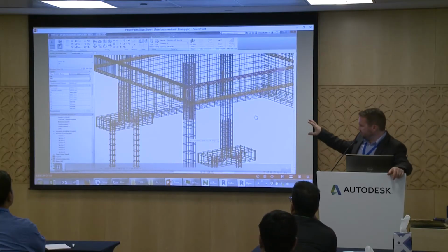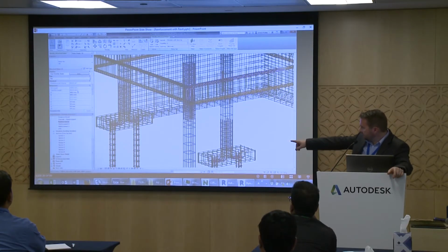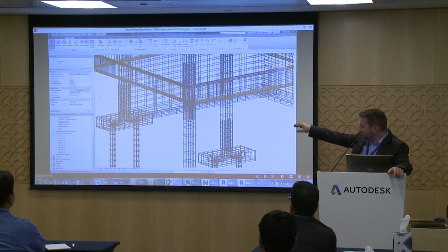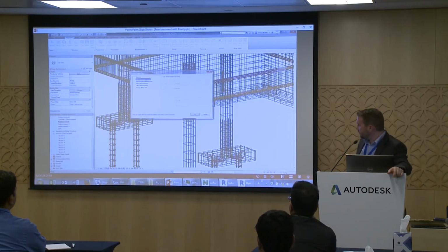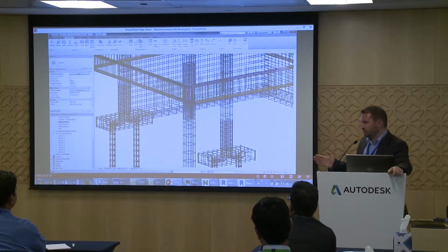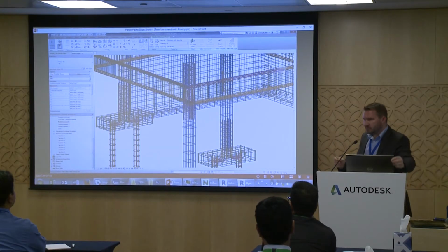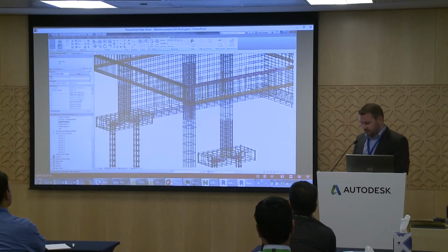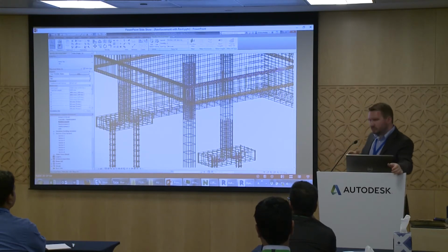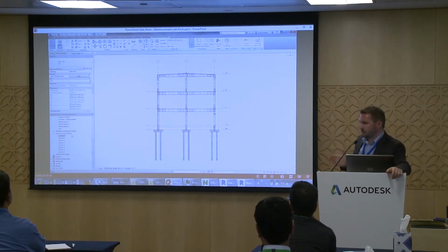So here, maybe the resolution. Here you can select. Here you have the distance of the reinforcement. And after, in general reinforcement, you can round. And it's important because Revit will put the same number for exactly the same reinforcement rounded. Because sometimes if you do a little bit too fast, you have 1 meter and 1 meter 0.001. For Revit, it's not the same. So you have to round at one time. And when you round, after, you have the element.